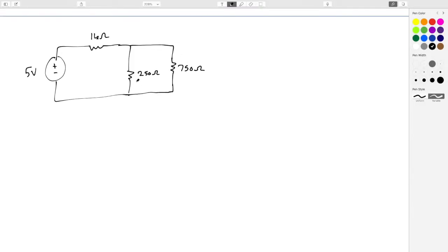All right, let's solve it one more way. We've grounded this node before, and we grounded this node. Now let's ground the one remaining one. Let's call that E0. Let's call this E1, and this E2. I'm going to label the currents the same way as before, just to make comparison easier: I1, I2, I3, I4.